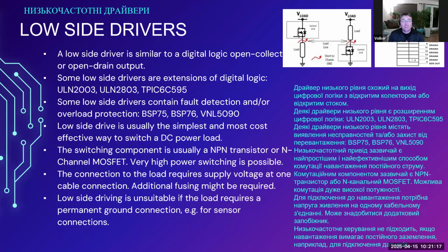Some low-side drivers contain fault detection and overload protection. I put some examples here, BSP70, BSP76. These do not provide fault detection, but they do provide overload detection. They are essentially safe against failure if a short circuit happens.